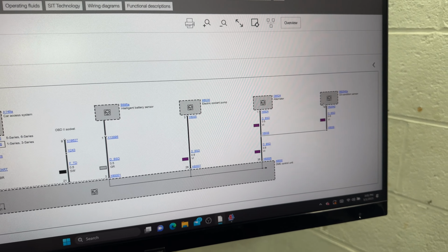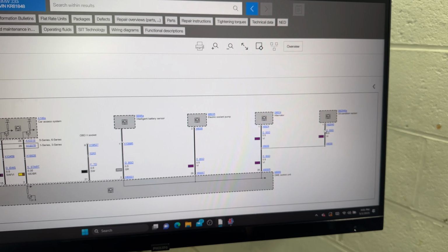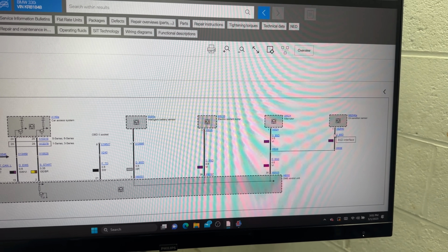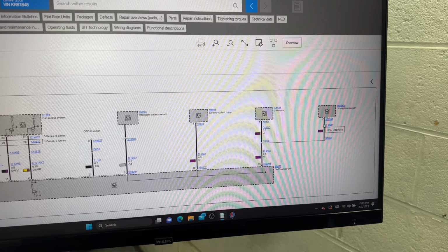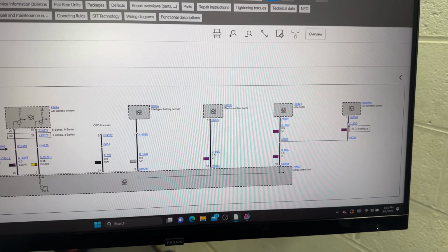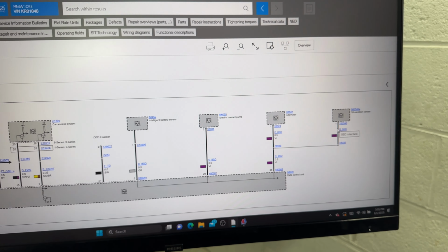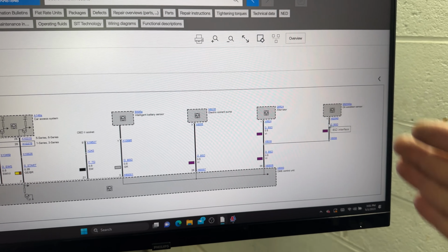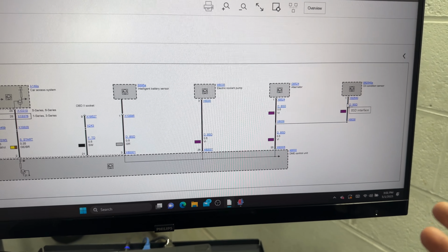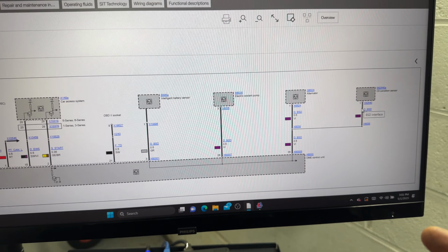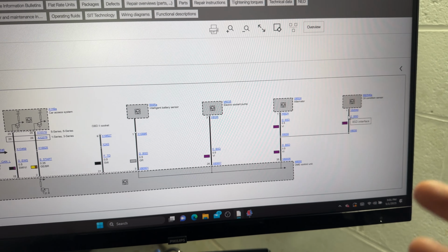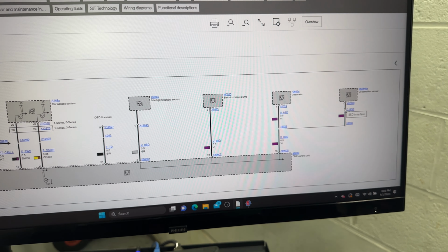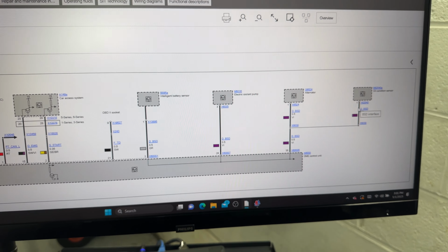So what I did is I went over to the oil condition sensor and I connected into the violet cable. This sensor is a three-wire sensor. You will have a battery voltage, a ground, and then the BSD signal. Even though it looks like a three-wire sensor, it's actually a network sensor. So this is like Ford is implementing these sensors now, like the coolant sensors, what they call smart sensors. But BMW, you can see, has been using this for a long time.